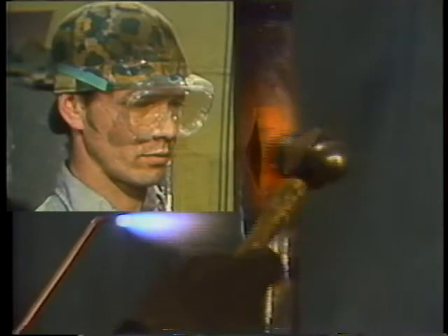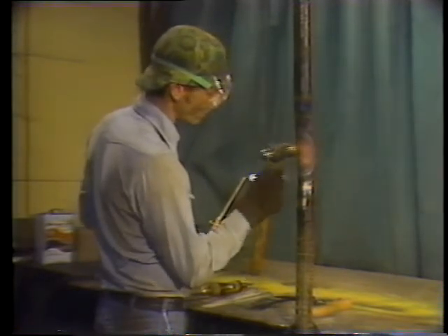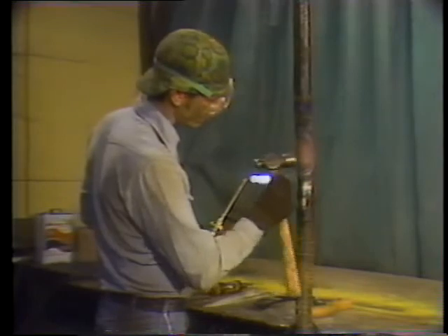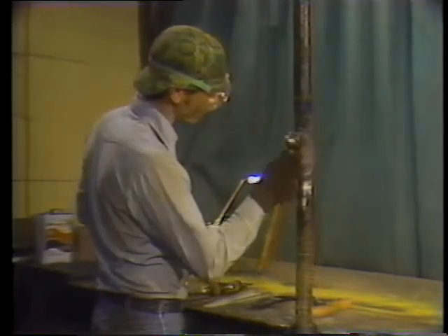If the tube cools off before the edges of the rupture are close enough together, the heating and pounding process will have to be repeated. The edges should be forced as close together as possible, but they don't have to touch. Take care not to pound so hard that you dent the tube. That can restrict the flow inside. Once the edges are as close as possible, they're prepared for welding by grinding them smooth. A V is made in the opening at a 35 to 40 degree angle.